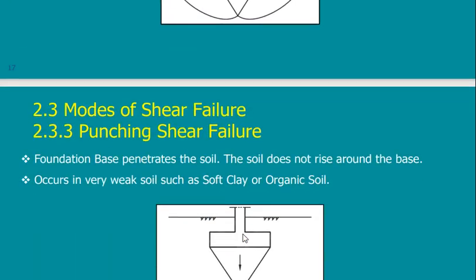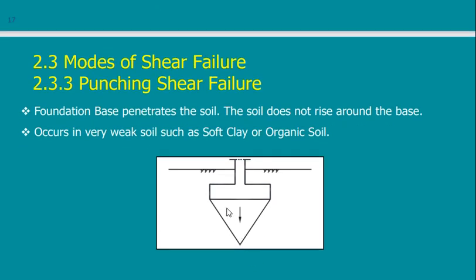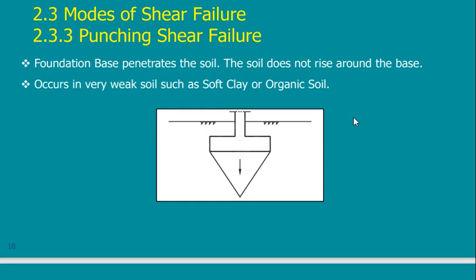The extreme is very, very soft soil, very weak soil. So this is the shape. The load will only affect the triangle beneath the foundation. So this is called punching shear failure. So you have general shear failure, which includes everything, or local shear failure for softer soil, or punching shear failure for very soft soil. This is just some information, because once we start doing a problem, we have to know which one to propose relative to the type of soil that I have.